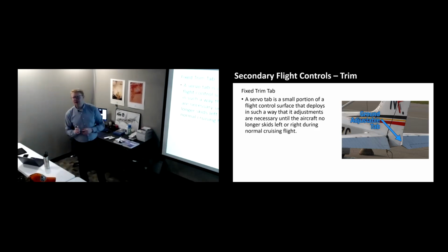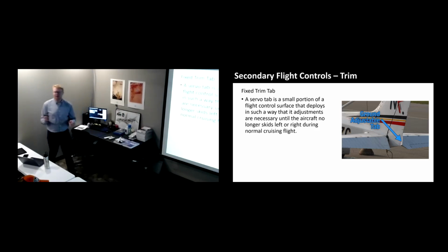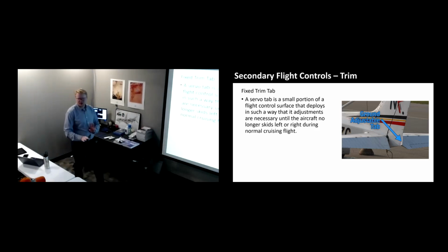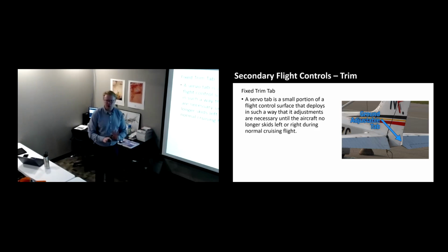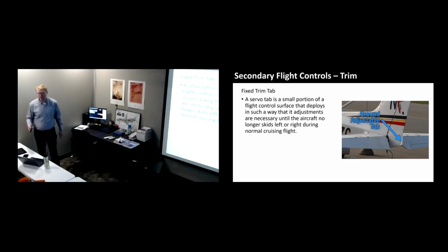You can actually change the entirety of the rudder input in the airplane. They don't want it neutral because then you have strange rudder inputs the majority of the flight. They want just input during high power settings. Reason being, they essentially want cruise flight to need very little input. Otherwise, you'd be holding your foot in the entirety of the cruise flight to balance itself. It's designed for comfort. Like I said at the beginning, normal feel for most people.